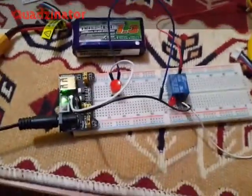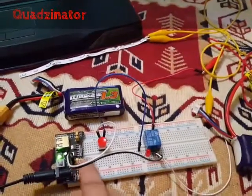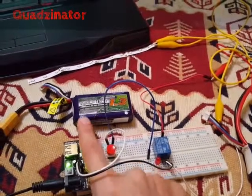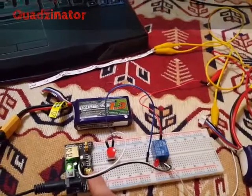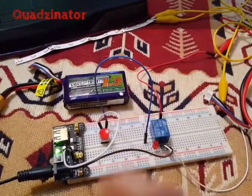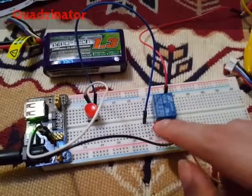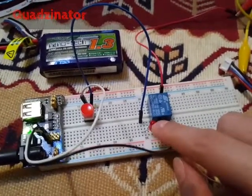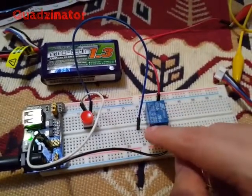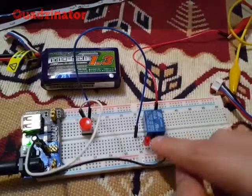Nicely put here. Alright, so what do we have here exactly? We have a 5 volt source. Of course, this is an 11 volt LiPo battery connected to this down converter, which outputs 5 volt. So we connect the 5 volt to the switch, and then, as we said, to pin 1 and pin 2. I connected this small LED, which operates only on 5 volt, in order to show you that I'm controlling a high voltage circuit using a small voltage circuit.